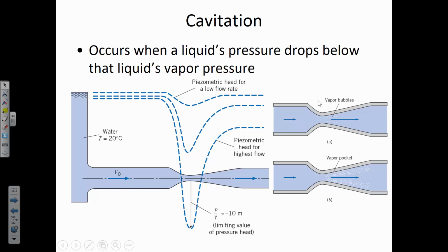Cavitation is not uncommon in ships or in boats, at the propeller that moves the ship through the water. There can be a low pressure section on the backside of an impeller. It can happen in pumps a lot. We have to be careful in the hydraulic design of pumps because negative pressures can occur.